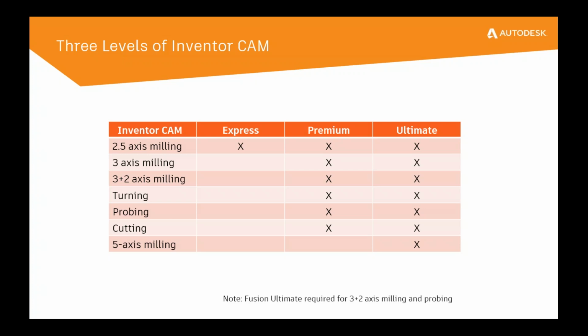Premium is going to do 2.5-axis milling, 3-axis milling, 3-axis milling with A, B, or C positioning. They call it 3+2, where you have a rotary table or a rotary indexer. We can run G-code to turn those indexers and position any way you want in 5-axis. It's not full 5-axis simultaneous motion, but they call it 3+2.